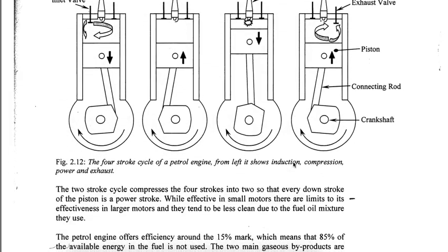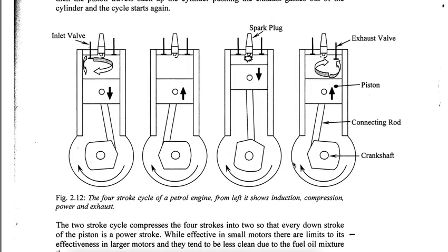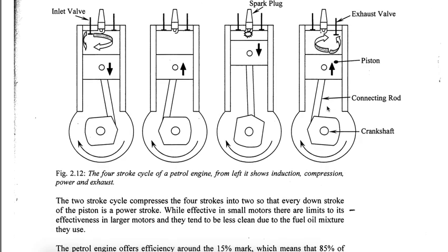I'll talk about that. Okay, we're going to learn about the 4-stroke engine process. So some of you guys who know about cars will already know this. But basically, there's 4 pitches. Don't be confused by the fact there's 4 pitches and the fact that a lot of cars have 4 cylinders. Even if there was only 2 cylinders, what it's showing is 4 different things in time. This is the first step in time, second step in time, third step in time, that sort of thing. So there's 4 steps: suck, squeeze, bang, blow. Intake, compression, combustion or power or drive or something like that, and then exhaust. So they're the 4 strokes.